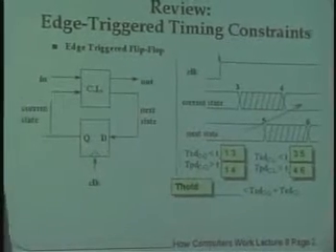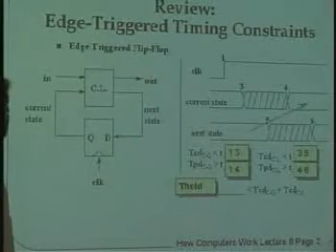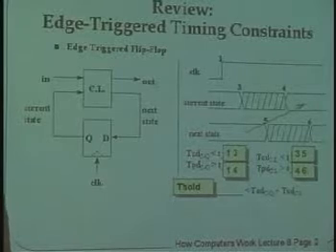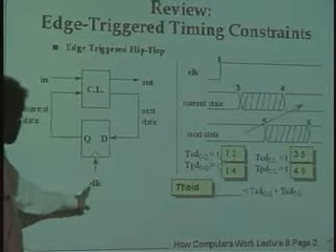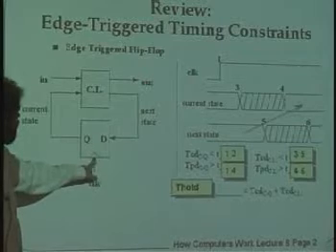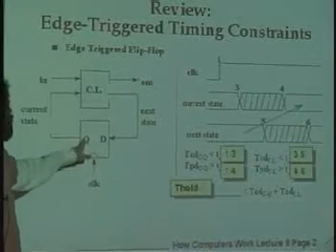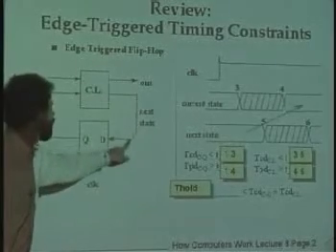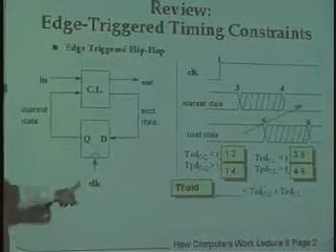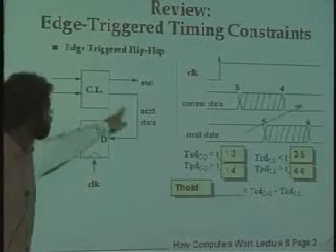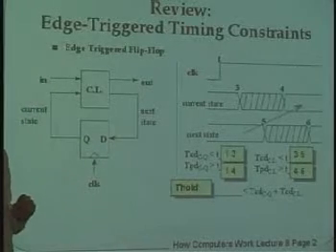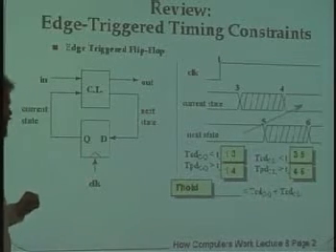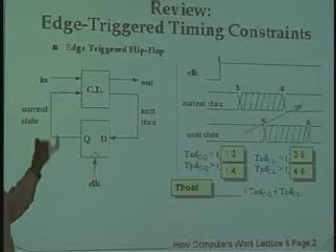And if you remember that there were certain constraints on the timing having to do with this feedback loop right here. And the first constraint was one saying whether or not the loop would work at all. And it was a question of, as soon as this clock goes off, then contamination begins to affect this Q output here. And as soon as this gets contaminated, then contamination flows through the combinational logic and comes back around here. And we wanted to first ensure that that kind of wave of contamination that goes through here did not happen too quickly. Because after all, just like a camera, we're blessed with an expert here on cameras, there are setup and hold times for this flip-flop.